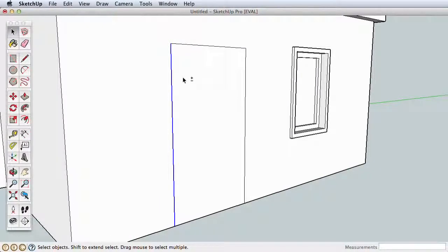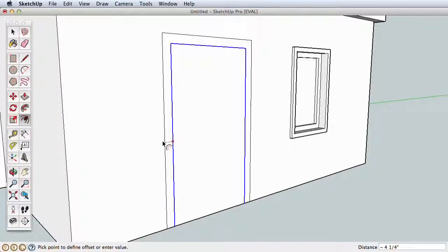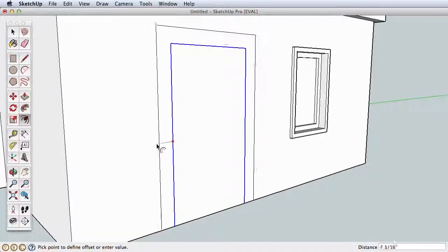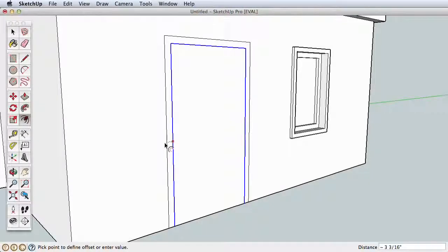Use the Select tool to pick one door edge, then holding the Shift key, add the other two edges. With these edges selected, the offset tool will focus and only work on those edges, so we don't have any problematic edges below our house and can correctly create the door frame. Pull the door frame out so we can use it in our next example.